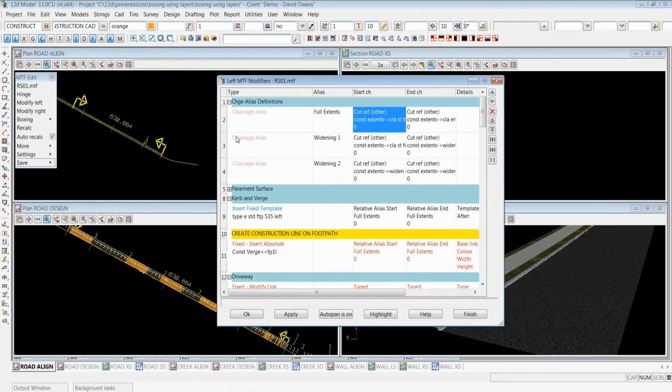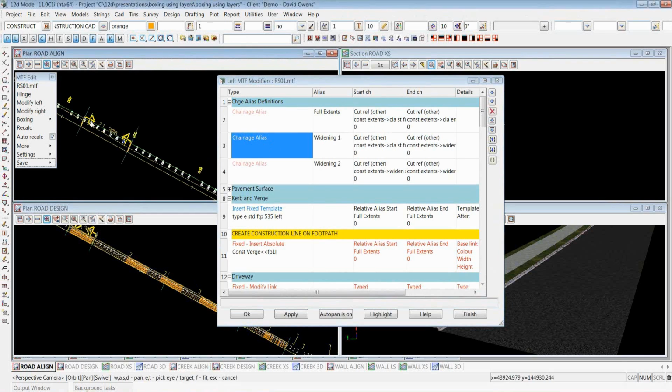And then as you start to build up the design and you realise you need to introduce a few other things, so in this case I had a couple of areas of road widening rather than just full pavement. Again, simply by drawing a couple of lines and saying wherever those lines intersect with a reference, that's where these different areas are going to start and stop. So I reuse these start and end changes throughout the course of the project.